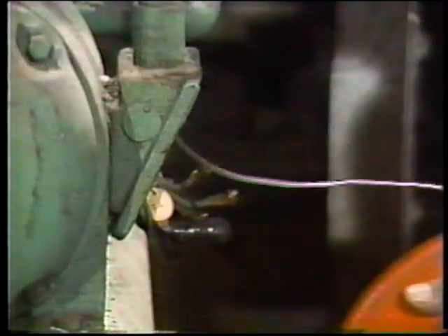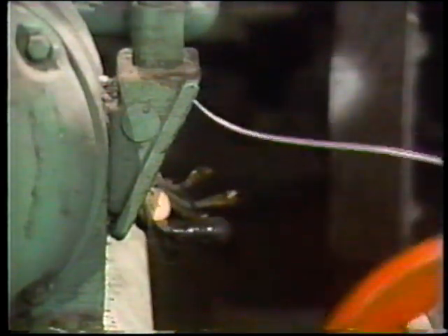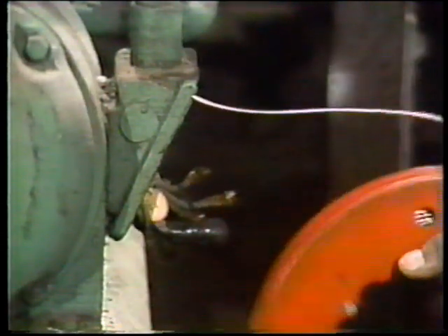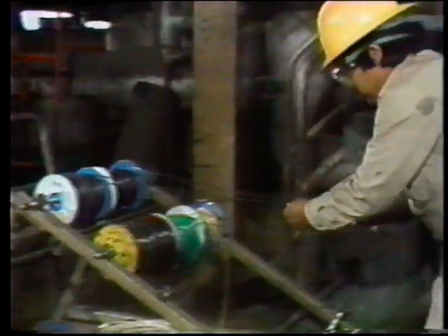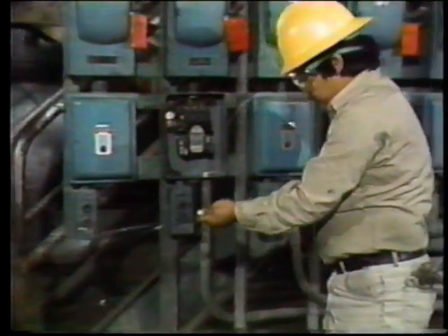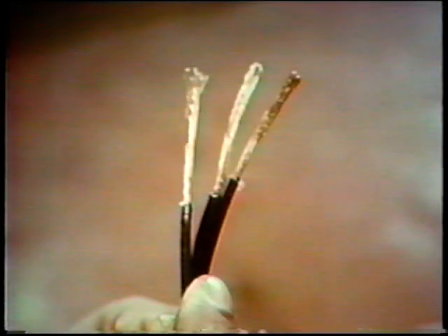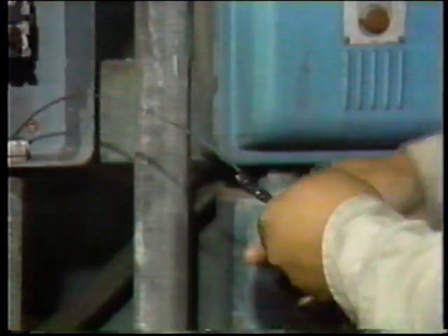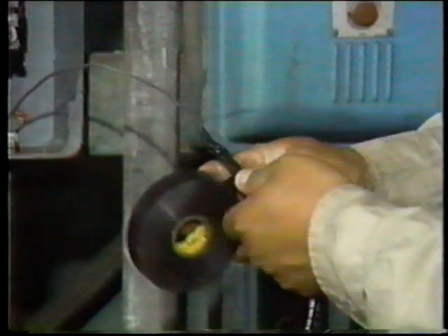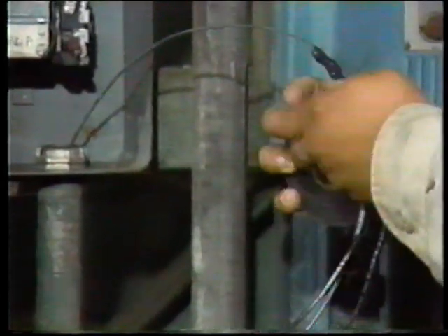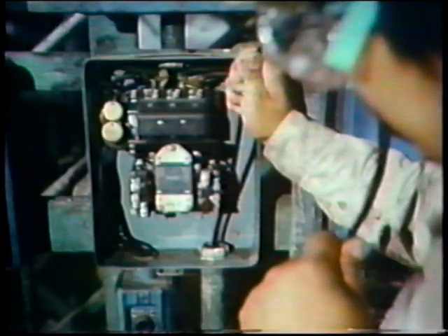Once he's got the fish tape through the conduit, the conductors will be fastened to the hook at the end of it. Rod, another electrician, is going to help Bill. He'll strip off a few inches of the insulation, then thread the conductors through the hook and fold them back. Then he'll tape the ends of the conductors in place. This will ensure that the conductors don't get separated from the hook, and it'll also help to make it easier to pull. Now, Rod's going to help Bill out by feeding the conductors into the conduit.